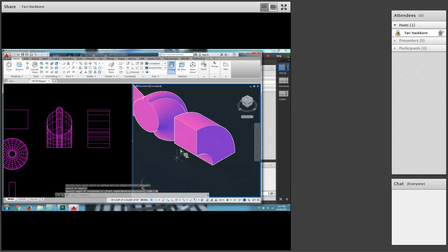I didn't have to make this one into a region. A rectangle automatically has area. It already has a surface area. Sometimes the revolve doesn't move in the counterclockwise direction like it's supposed to. If this happens to you, then you just type -90 instead of 90. Okay, a revolved paper clip holder. This one takes a while, okay?